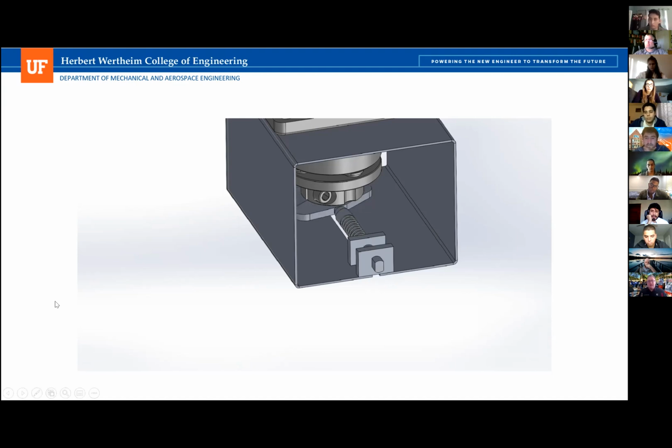It's got a lot of side load, so that side load transfers to heavy amounts of friction. And then as it goes down the other side of the cam, it can lose contact because the cam surface is moving away from the rod faster than the rod is descending on the cam.